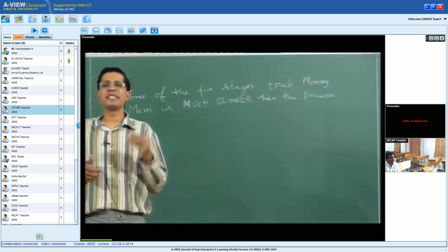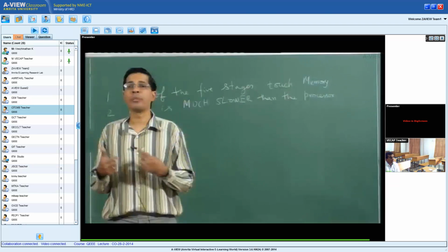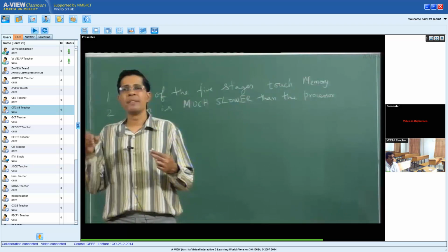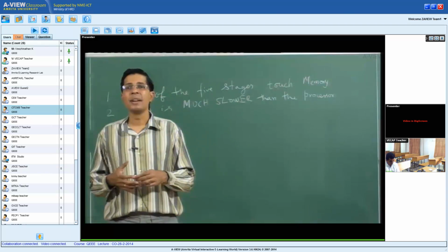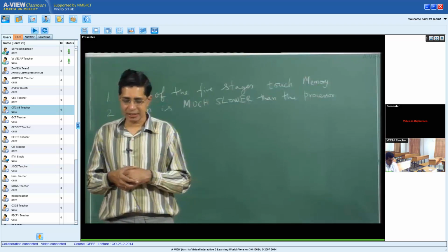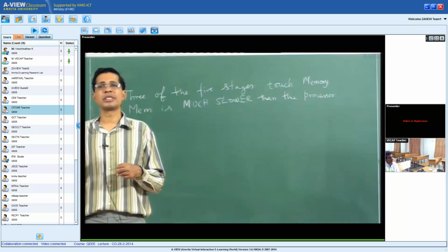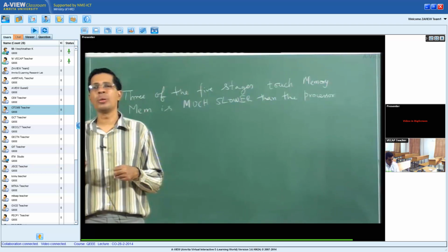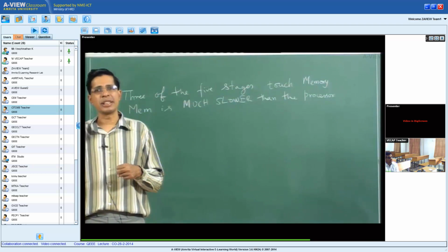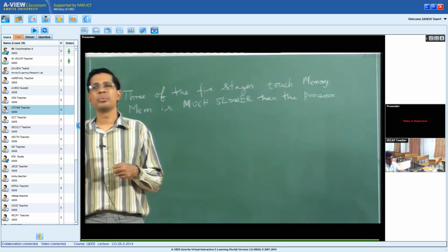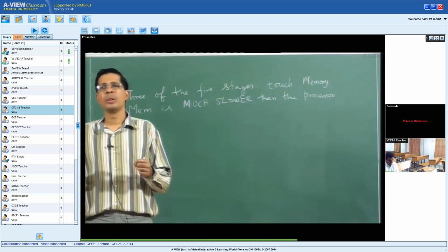When we looked at the 5-stage pipeline, one of the things we told was fetch an instruction. Fetch an instruction from where? We said there is a program counter which tells the address where the instruction is stored. Similarly, fetch the data from memory. From where? We have an address from which the data should be fetched. So if my program has to execute correctly, you should clearly know where the program is loaded, from where should I get the data, where should I store the data, from where should I get the instructions. So I should really know where my program is loaded.